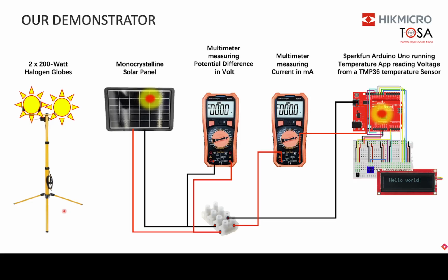Let's say on the right hand side, you see the hotspot created. Let's say there's something happening on the panel between the cells that shows up as a heat image. If there's a connector problem, that shows up as a heat image. Any connection along there, you'll see a heat image coming off, and if there's another component on the board, it'll show up as a heat image.